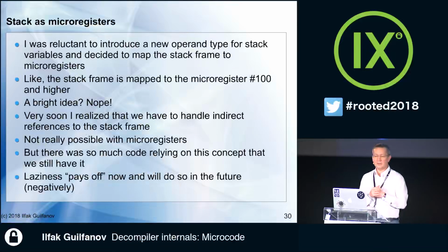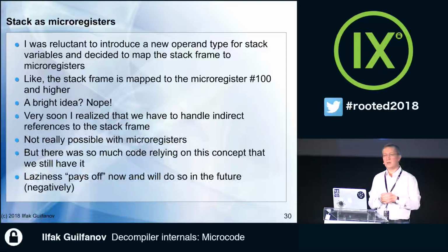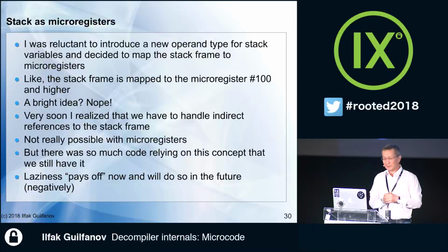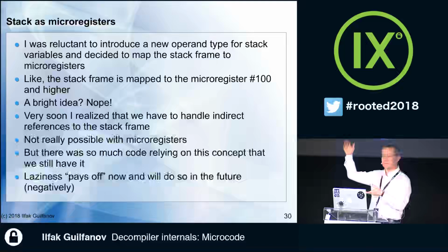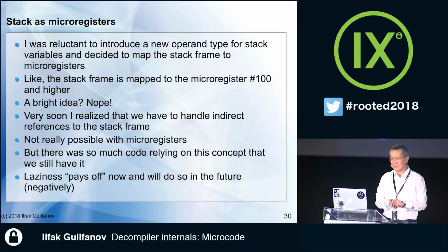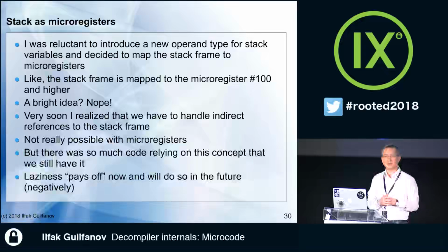In the future, I had this bright idea, "bright" in quotes: why not map the stack frame into these microregisters? Since we have plenty of them, we are not limited by anything. We could map everything to the microregisters, and therefore we just use the same logic. We don't need to implement a special logic for stack operands.